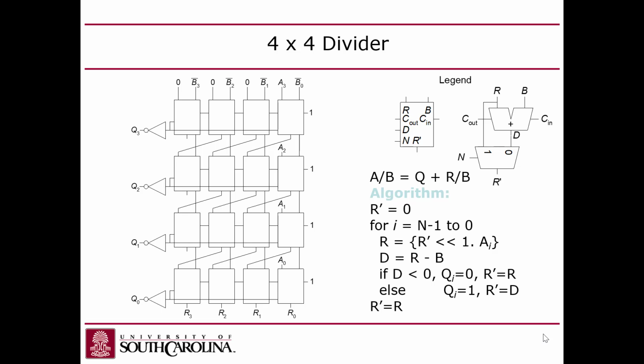And then this mux is taking care of the restoring process, where it's taking R, which, remember, R is the first input, that's the quotient or the remainder, what will eventually be the remainder. This mux is restoring the original value of that if this D is negative.